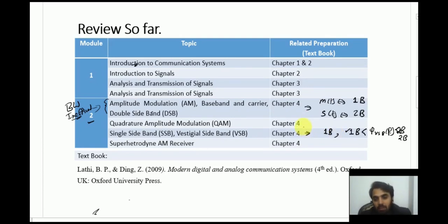Then there is another aspect, like if we can have multiple signals, we can multiplex them in terms of in-phase and quadrature phase. So we can send two signals, and those two signals combined would take 2B bandwidth. So that is another scheme, right? It depends on the application what you want to use, and this is QAM: 64, 256, 1024. 1024 is basically used in 5G right now in downlink. So they are still there in digital TV and elsewhere, right? So all of them are still there.